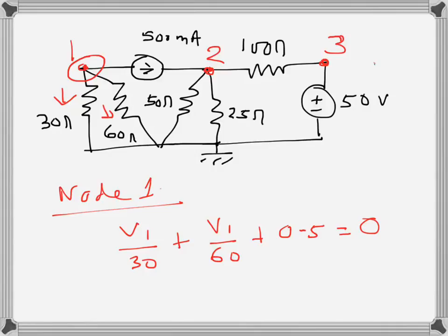So that's there. Now we observe that because of the presence of this current source instead of a resistance or some other element here, we can directly write the outgoing current from this node in this direction, and that's why the other node voltage does not come into the equation, and we have an equation where we have only one unknown, so we can directly find that unknown.